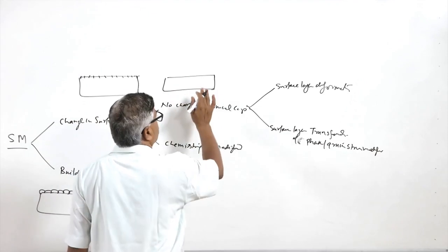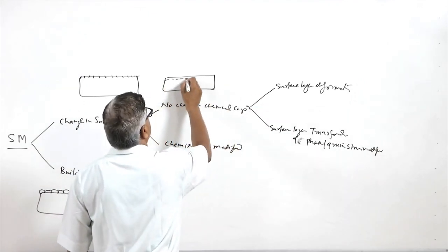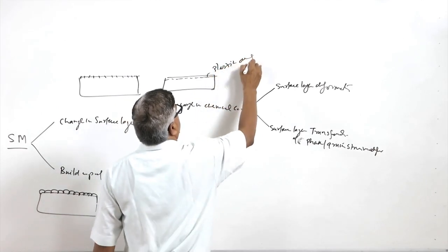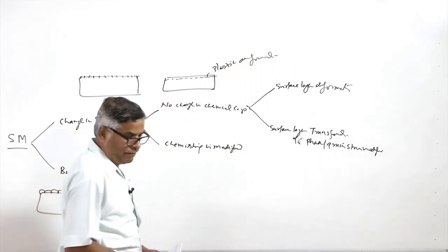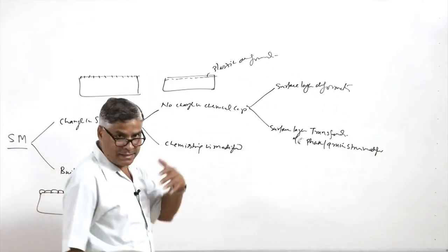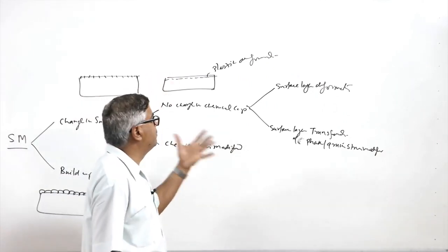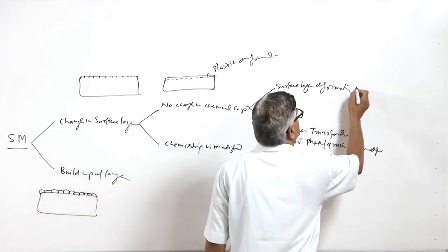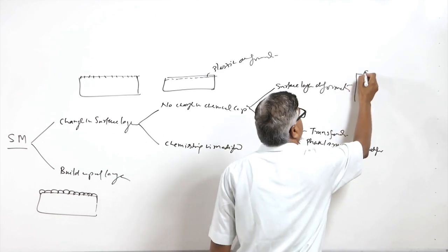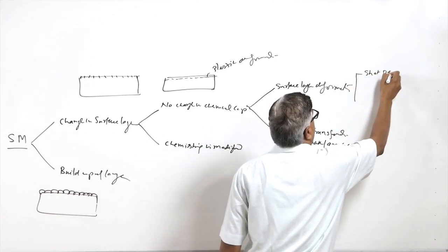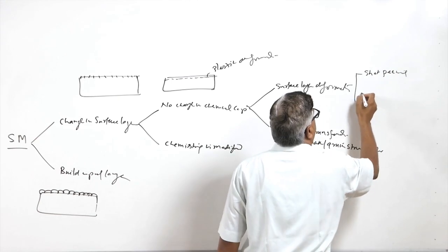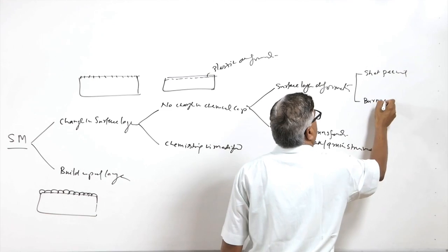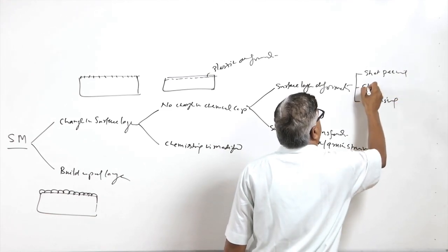In the first, just the near surface layers will be subjected to plastic deformation, so that a work hardening effect is realized and the surface gets strengthened and hardened to take up higher surface loads effectively. Under this category there are a few methods like shot peening, burnishing, and sandblasting.